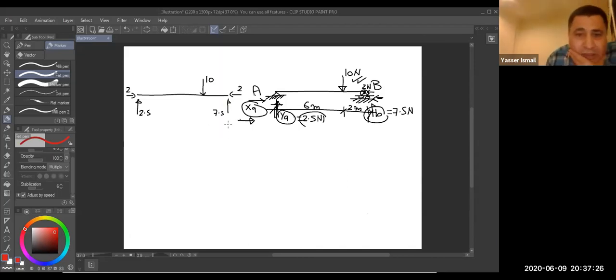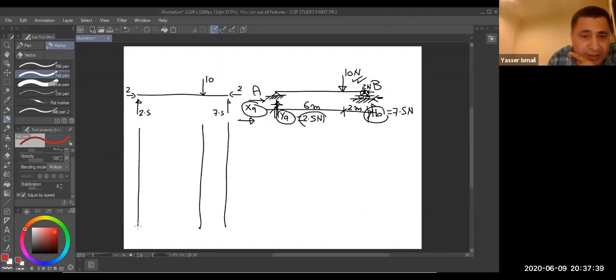Now I have all the external forces and the reactions due to them. I will draw the internal forces. Let us start with number 1, the normal force diagram. Normal force is tension or compression. This is my free body diagram, and the body is compressed. If you take any section here, consider it a rectangular or square section.